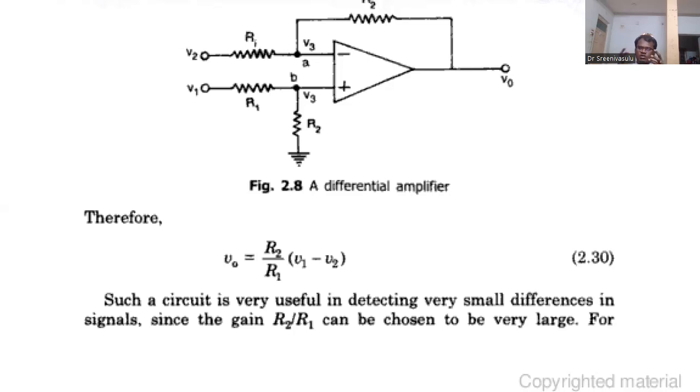After designing this op-amp, we calculate the common mode rejection ratio for that purpose. This Ac should be a very small value, that is our desired case. Whenever it is very small, then only will our CMRR be higher. Whenever the op-amp CMRR is higher, that is a good amplifier, a good op-amp. That's why you see this common mode rejection ratio.